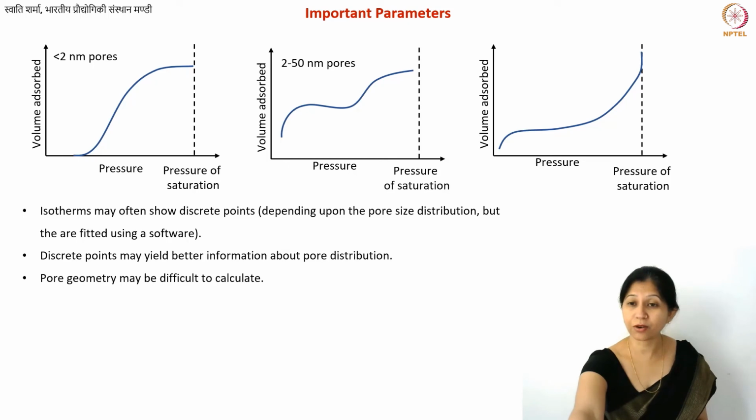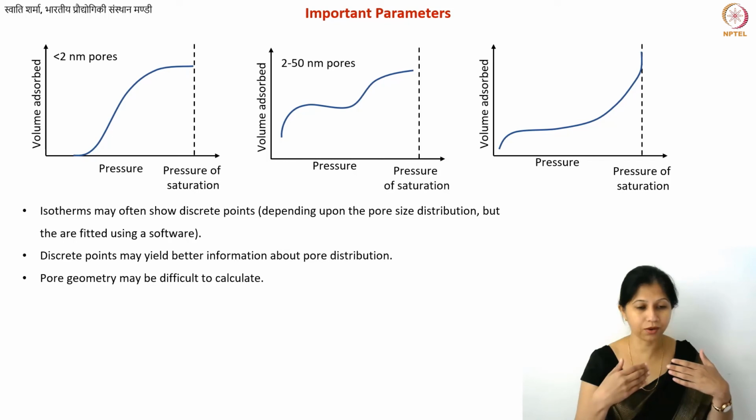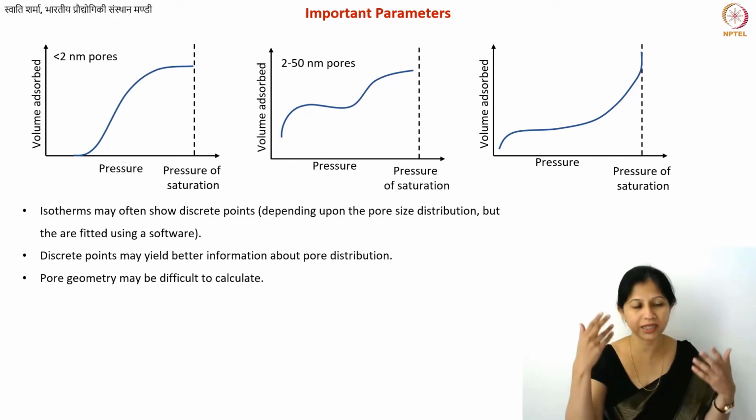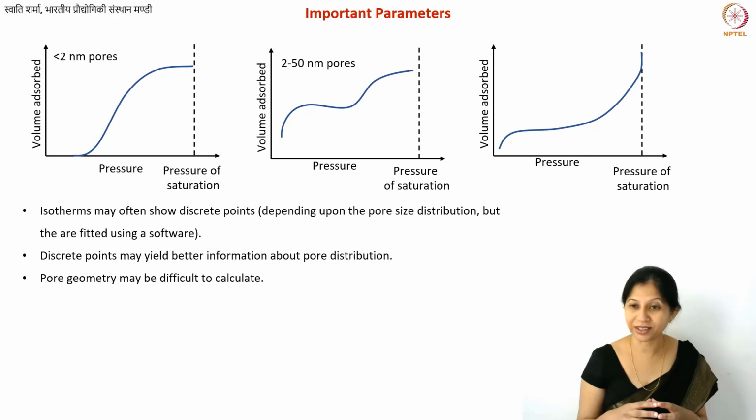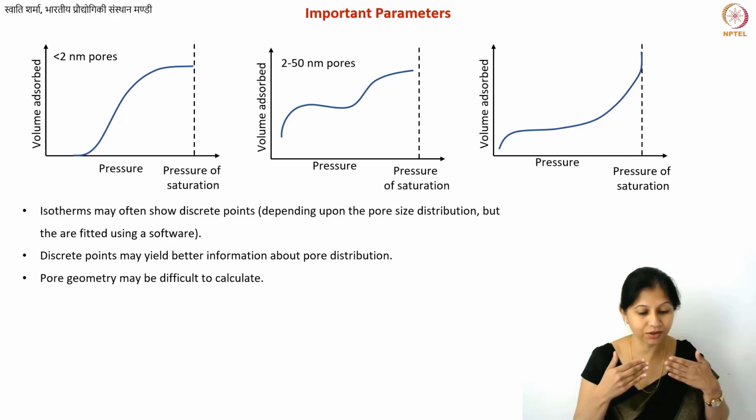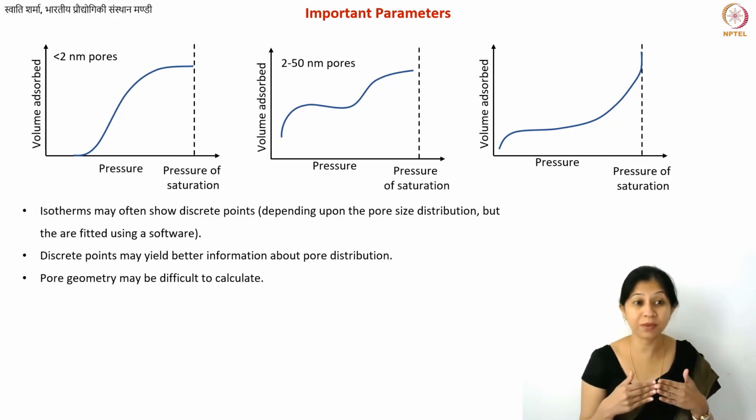Of course, the closed porosity you cannot guess from here. By the way, X-ray tomography and MRI, although these techniques are challenging, have the advantage that you can also get information on the closed porosity, as you have slices of images. Basically, when you take the MRI of your brain or X-ray of your hand, you don't have to cut open the brain, right? This is non-destructive imaging. That is why these techniques are very useful. They are non-destructive techniques that can also give you information about closed porosity. So if your material has a lot of closed porosity, you might want to try one of these techniques.